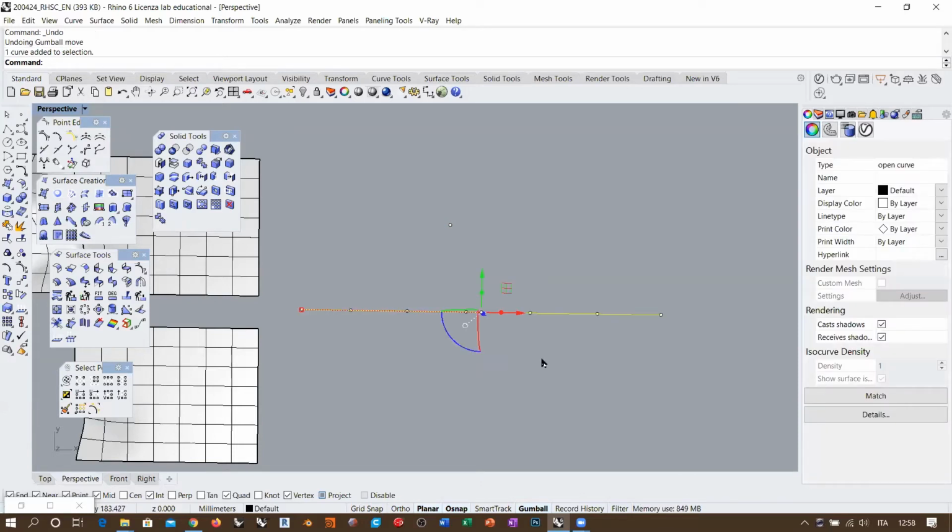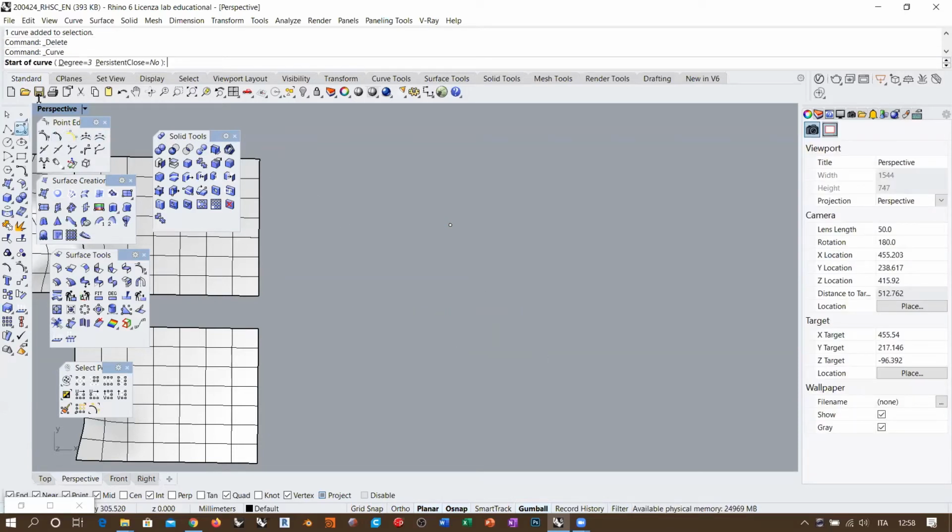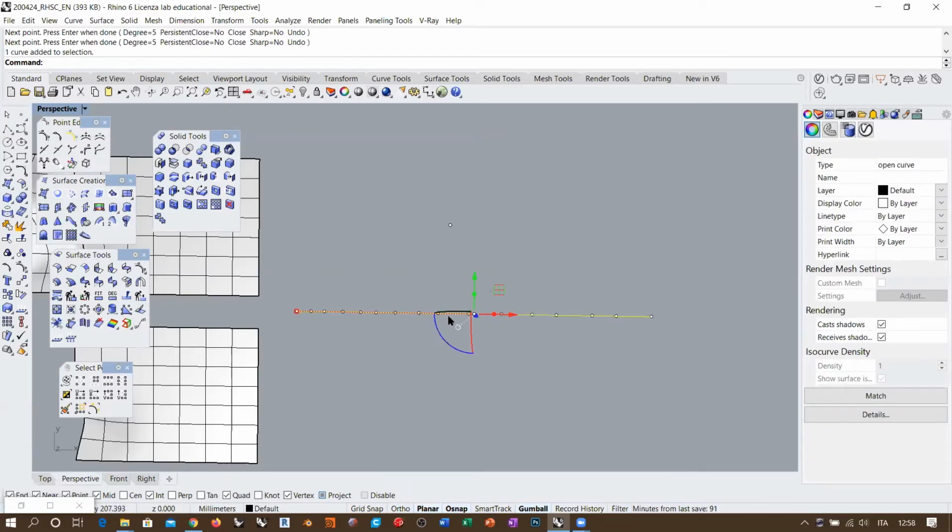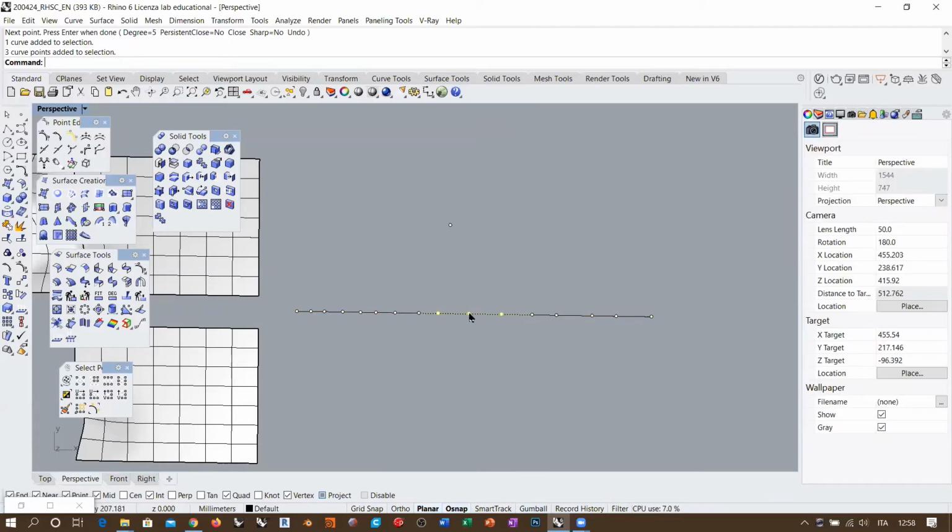What happens if I take another NURBS curve, but I'm not going to use degree 9, but degree 5, okay? So I'm going to use degree 5. I know that I must provide at least 6 control points in order to maintain the degree 5, okay? So I'm going to use quite a bunch of control points. I don't even care about how many control points, right? But I have this curve, which has degree 5. And I take this control point here. Let me get rid of the gumball. So I get this control point here. I take 3 of them, and I want to move them here.